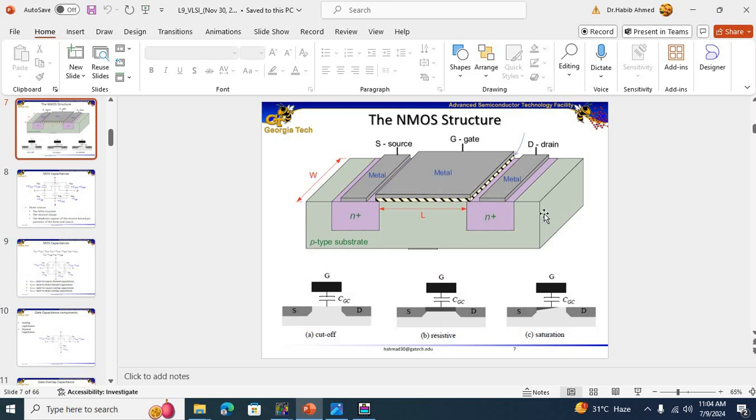Let us talk about the conventional field effect transistor. In a conventional silicon based field effect transistor, we actually have a substrate. The substrate is lightly doped, and the drain and the source are heavily doped. So for example, in this case, this is an N-type metal oxide semiconductor field effect transistor, which means that the channel is made up of N-type materials. The drain and the source are heavily doped N-type materials. The substrate is lightly doped P-type. And similarly, we have a gate dielectric material. Then we have the gate contact. We also have the drain and the source contacts.